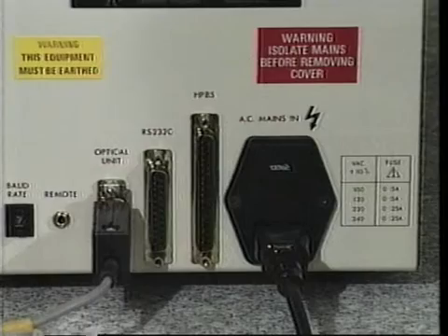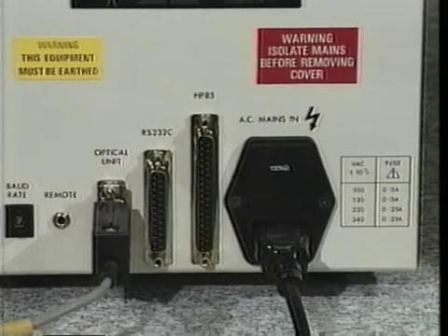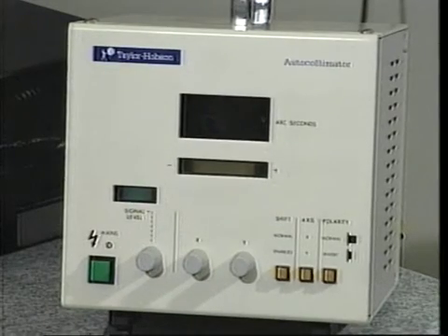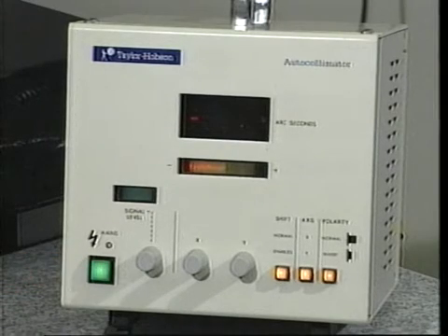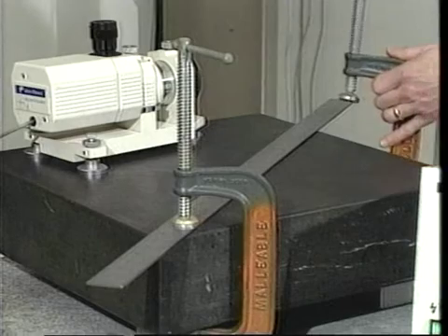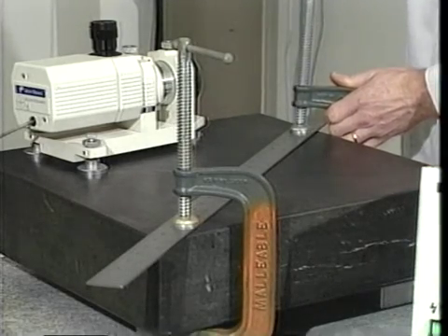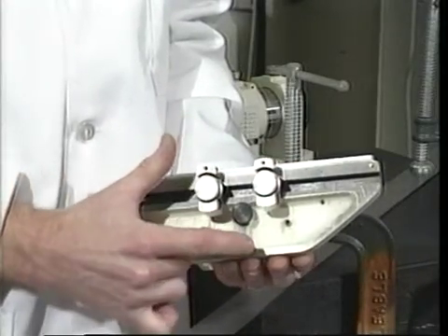Connect the console's power cable to a power outlet, making certain that the supplied voltage agrees with the voltage selected on the rear of the console. Turn the console on by pressing the mains push button. Allow time for electronic stabilization. Use a straight edge to ensure that the reflector is moved in a straight line along the measurement path. Again, note the use of kinematic mounting. The sled has 3 feet.